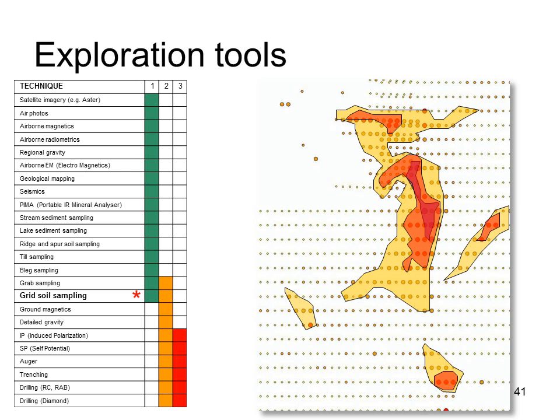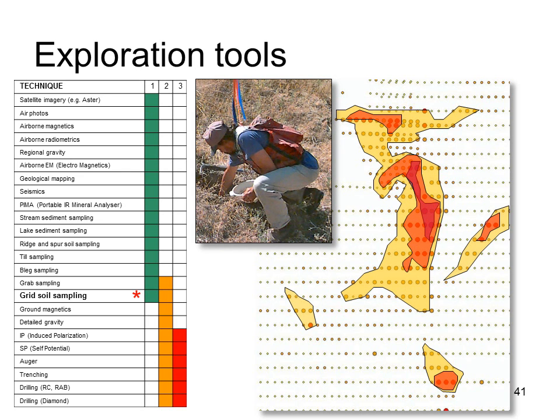Obviously, the technique requires soil, so it's good in tropical and subtropical areas where good soil profiles are developed. Soil sampling is an excellent way to define the limits of shallow mineralization. There are a couple of caveats. Beware of soil creep and dispersed anomalies on slopes. Ensure you are sampling in situ soil and not transported soil, and ensure that the samples are taken of consistent material.